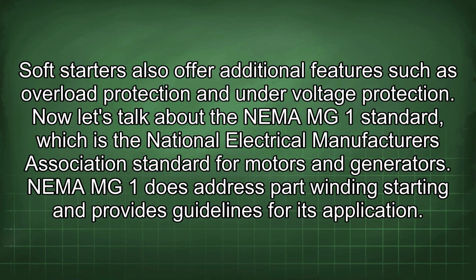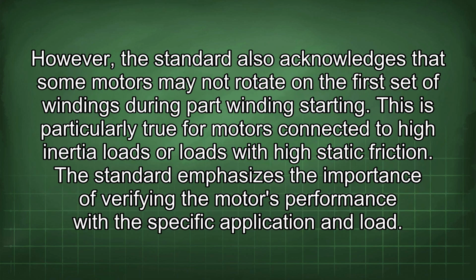Now let's talk about the NEMA MG1 standard, which is the National Electrical Manufacturers Association standard for motors and generators. NEMA MG1 does address part winding starting and provides guidelines for its application. However, the standard also acknowledges that some motors may not rotate in the first set of windings during part winding starting. This is particularly true for motors connected to high inertia loads or loads with high static friction. The standard emphasizes the importance of verifying the motor's performance with the specific application and load.